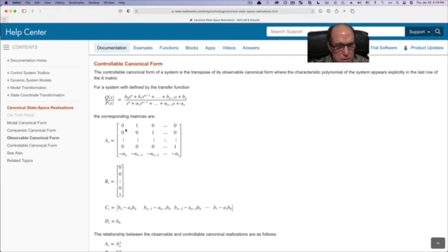So we found it on the top row. So what we had was a controllable canonical form with a permutation. It's just like renumbering the states oppositely. So to just flip this up down, you would just renumber the states in the opposite order.